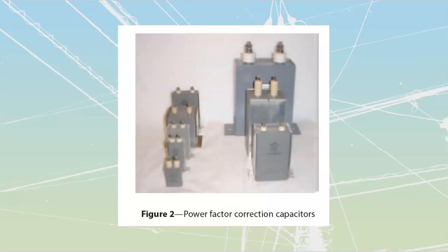So it is more common for this to happen the opposite way, where we have our 60 hertz system, but what we've bought is a 50 hertz cap that we are going to be utilizing. If we buy that 50 hertz capacitor and we try to use it on our 60 hertz system, we are going to have an increase in our number of VARs.